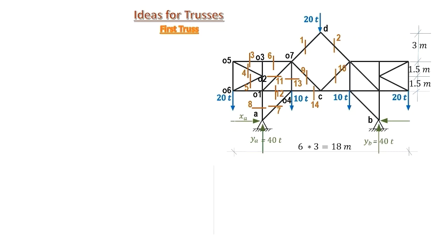And since the truss is symmetric, YA equals YB equals half the 80 tons, so each carries a vertical reaction of 40 tons. Now we need to calculate XA, the horizontal reactions at A and B. This couldn't be done unless we have moments about C.